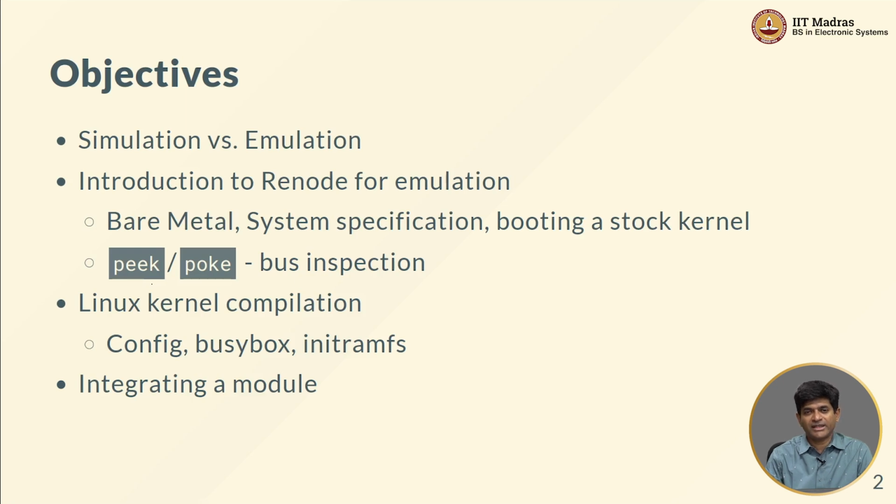And finally, we will take the demonstration module that we had from week 3, which is basically an interface to the smart timer, and walk through the process of how that can in turn be connected with Renode as a peripheral and then used for emulating a complete system along with appropriate peripherals.